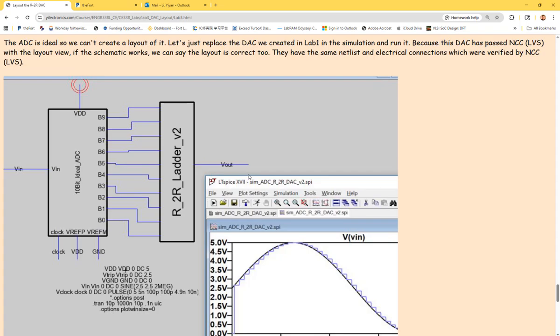So if you do DRC and LVS, for example, for this stack, we see issues. And we know the issues will be just the connections between the boxes, because inside the box is already done. The LVS and DRC are done. So we know it works. So if you see issues over here, there will be only like 10 problems or errors instead of 100. Make sense?